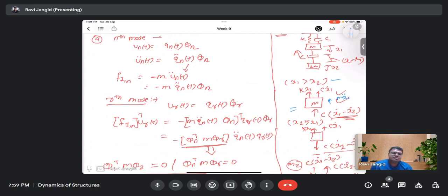Plus or minus in the solution is okay, but at least the free body diagram should not be confusing. When you make an assumption itself, you should not get the answer in the negative. The assumption should be such that we get the result in the positive direction, so that our assumption is right. I will ask them to take care from the next assignment. I don't know how that kind of mistake can happen, but it might be due to some human error.